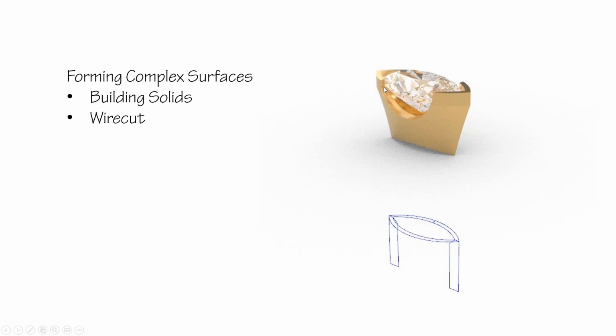Building solids, I'm also going to demonstrate wire cut, which is actually relatively new to me, although apparently it's been there since Rhino version 4. Part of my ongoing process, kind of like a Boolean difference, except it can be a little faster because you just use simple curves to do a Boolean cut on a solid.